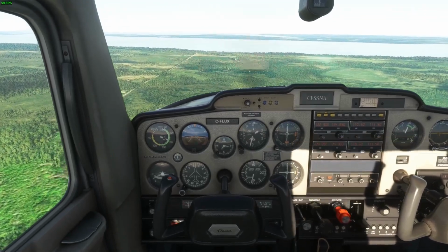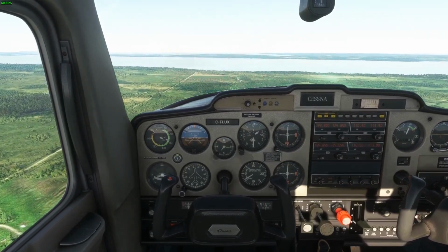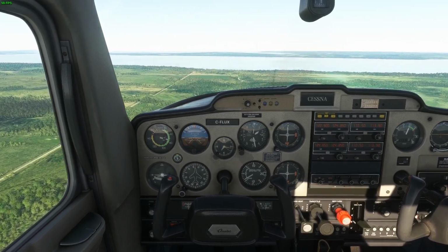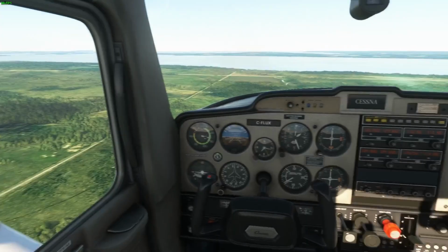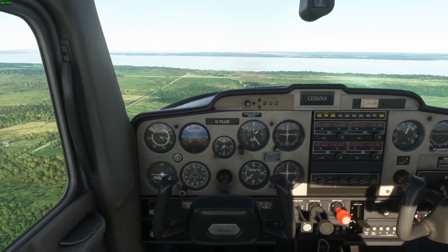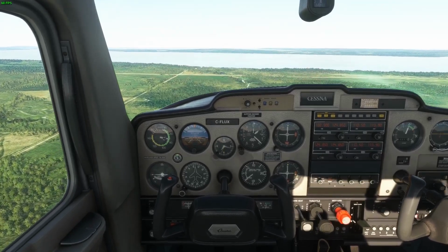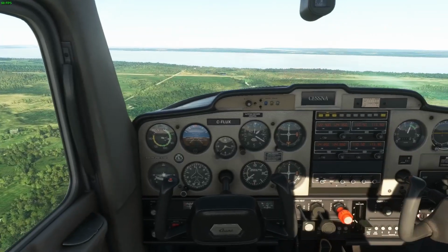Okay, so we're still about 700-800 feet above the ground, 700. Descending at 500 feet a minute, RPM is good. Airspeed is 70, that's good. Checking the position of the runway. So we want to turn when we're 500 feet off the ground and it's just about in line with the runway. If we do this right, those two will come together. So that'll be any time now.